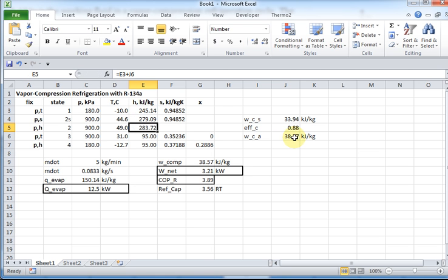All right. And then if you wanted to look at that temperature, evaluate temperature as a function of pressure and enthalpy. And then go to state 3. The pressure and the temperature were given, and you just look up the enthalpy as a function of pressure and temperature. You don't need this entropy, you can get rid of it. You don't need that S, but if you wanted to have it, you could put it in there.